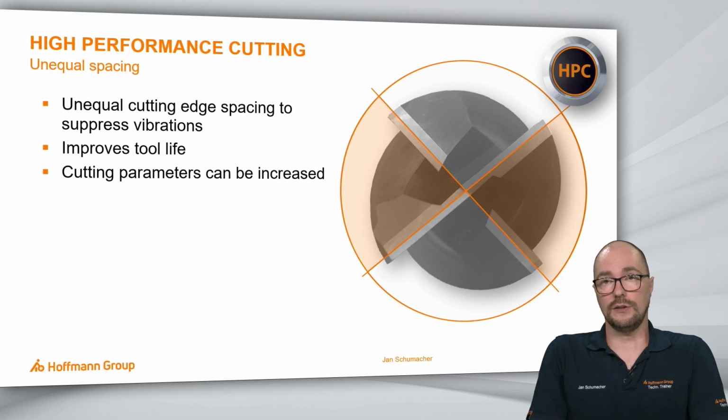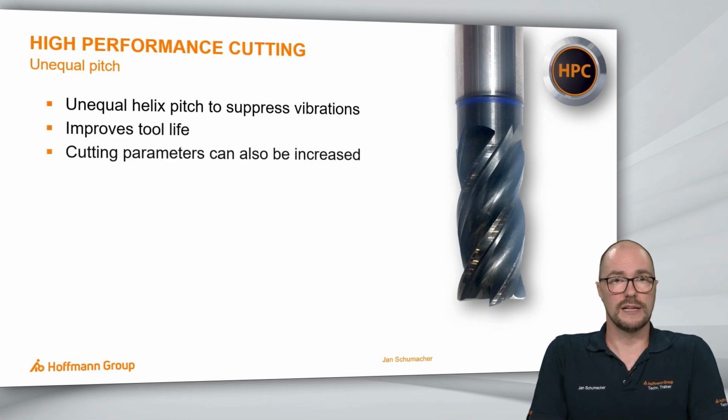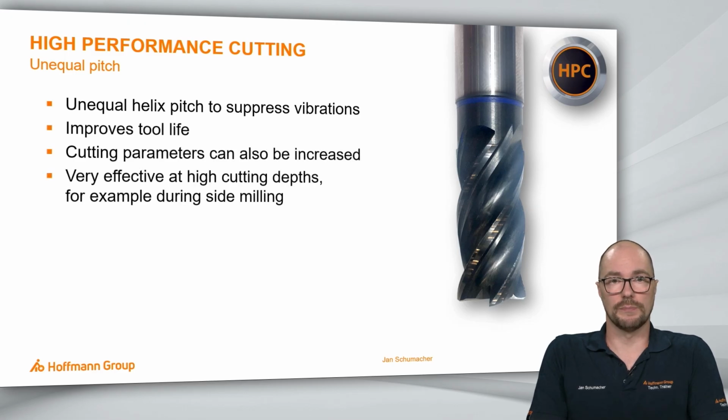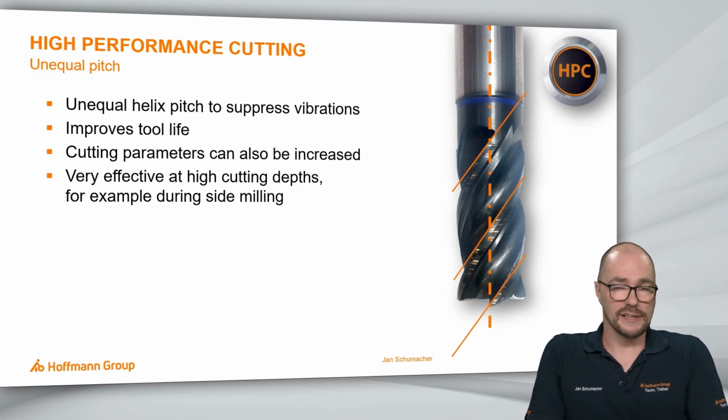Unequal spacing often comes with another geometric twist. This is an unequal pitch. I try to indicate that here. Here you can see the pitch angle of each of those cutting edges. And you can see that these lines don't end up being parallel. Well, this is not some mistake during grinding.